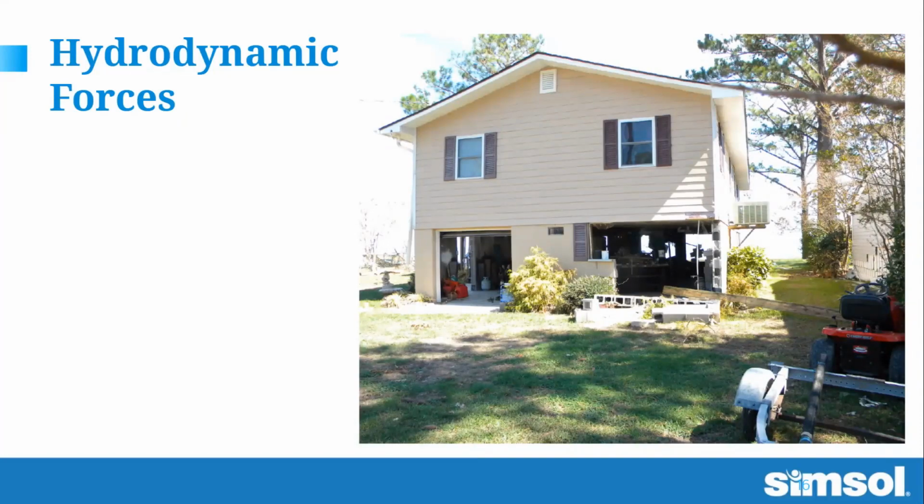I have a question for you, another one. Sure. Okay, so if we're looking at this building right here and we have piers, so it's an elevated structure. Yes. And when you look at the storm surge, you're going to see movement at the bottom. So you might see these piers leaning in the direction where the water was going. That's correct. The important thing to realize there, especially with a pile supported building, you want to look for plumb measurements where all of the piers, all the piles are listing consistently away from the direction of the water. So if it's on a beach situation, all of the piles should, the top should be leaning away from the ocean.